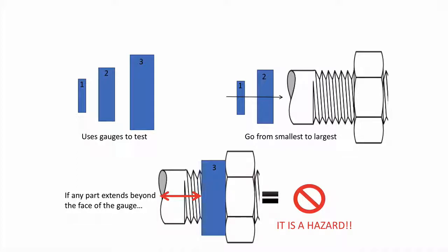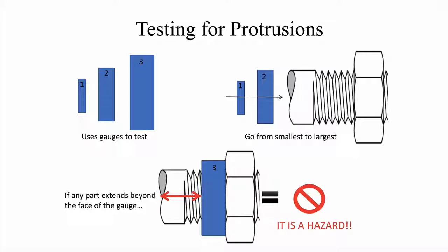If providers locate an exposed bolt or component on their equipment that may entangle children's clothing or cause injuries, providers should use gauges to test the protrusions. To test, place each gauge over any protruding item, starting with the smallest gauge first. Try to fit it over the component. If it does not fit, move to the next one.